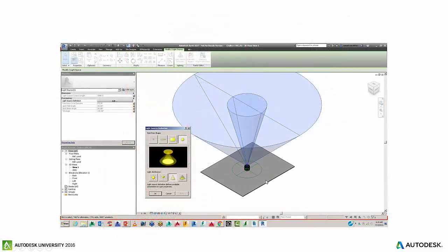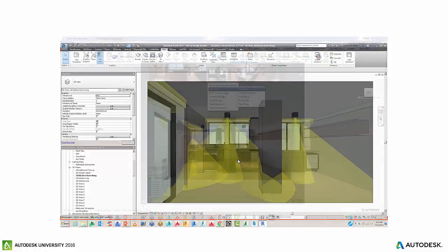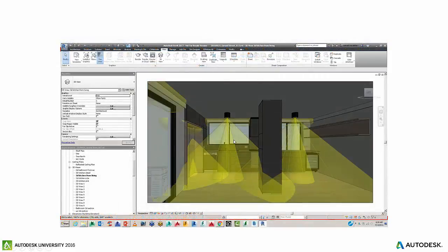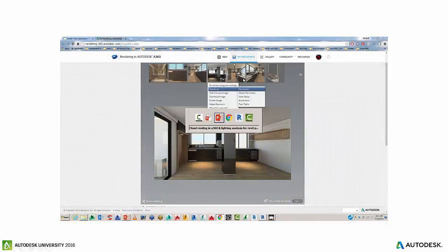This is the light family that I'm using, and this one came with a default spotlight. If you click the button next to that, you can bring in the IES manufacturer's data and load that into your library, and you'll move from this to the other display one, which is the IES web file.